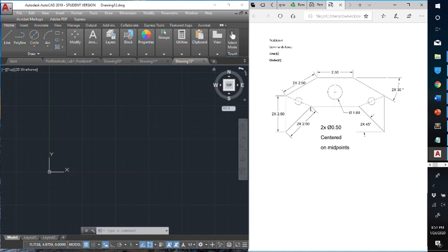So if I start over here, I'm going to make a line that is 2x, that's 2.5 in length, and it's going downwards by 45 degrees, or is up 45 degrees from the horizontal. So let's do that. So we want to have our dynamic input on again, and I'm going to click wherever I want to start, and I'm going to type in the 2.5, which is our length, and this time though I'm going to hit tab.